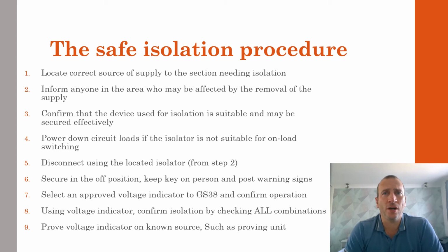It's important to start with the low voltage terminal first, since the circuit at this point is not proven to be dead. If it is still live at any point, then the lead not placed on the live terminal may also have a voltage and could result in a shock to yourself or someone else.